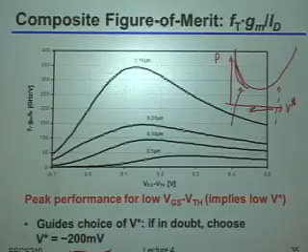Because again, I think you probably talked about this in, for example, 141, this is a so-called self-loaded limit. It's basically saying, as you keep decreasing that V star, your FT is going down, and if that FT gets close to the gain bandwidth you were trying to hit in the first place, you can spend as much power as you possibly want. You just won't be able to get that speed, because no matter how much power you're spending, the transistor driving itself just can't possibly hit that speed.